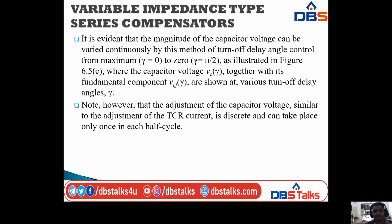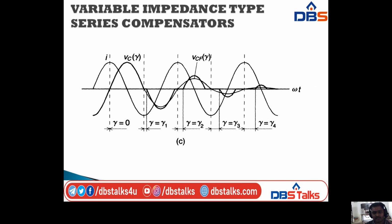So it is evident that the magnitude of the capacitor voltage can be varied continuously by this method of turn-off delay angle control, from maximum, that is gamma equal to 0, to gamma equal to pi by 2, as illustrated in the diagram. The capacitor voltage, Vc of gamma, together with its fundamental component, Vcf of gamma, are shown at various turn-off delay angles gamma. So this is a diagram representation of that.